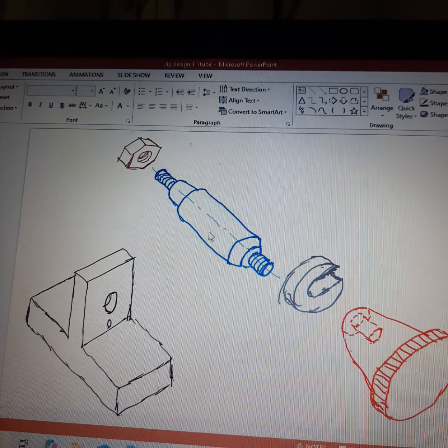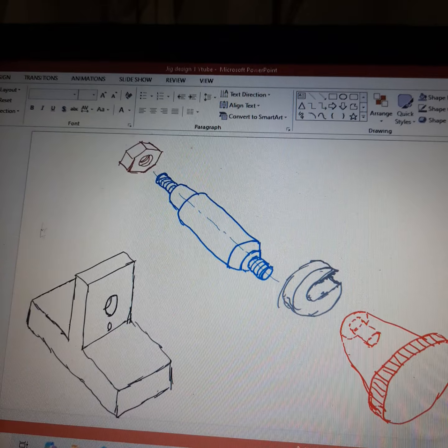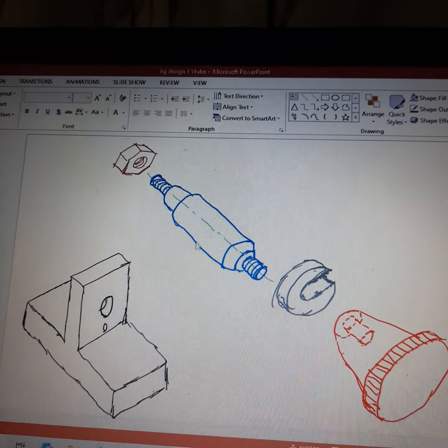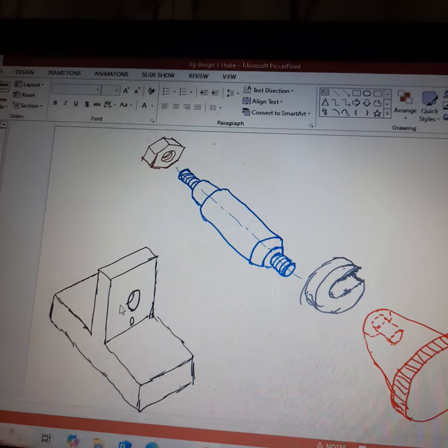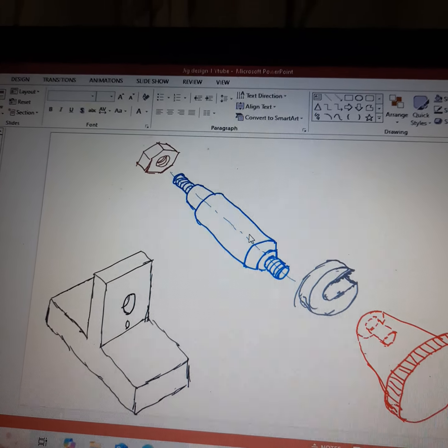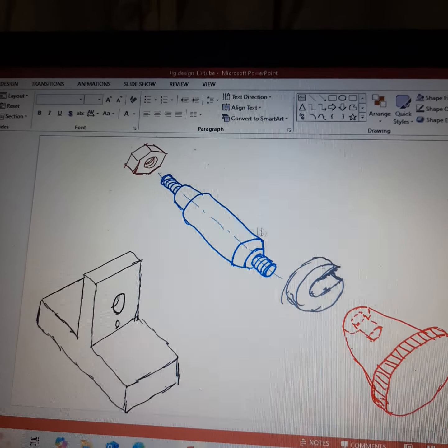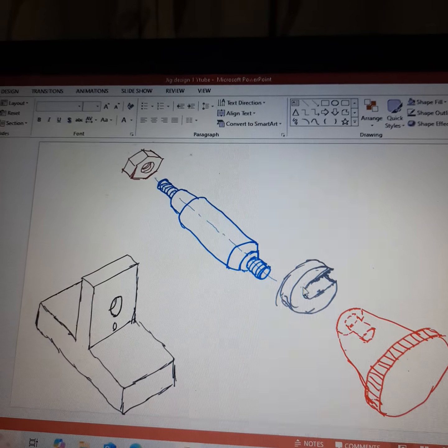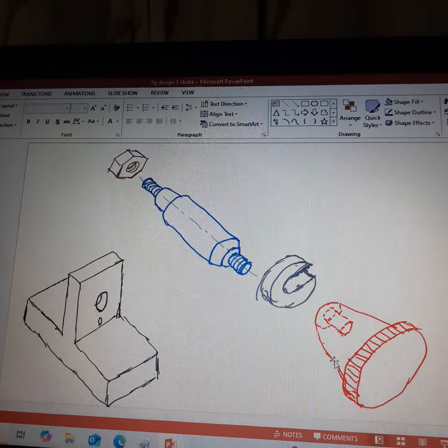On fitting this onto the vertical wall, from the other end we can use a washer and nut for holding the location post onto the vertical leg of the base. Once this is fitted, we can insert the component through this post, and for clamping we are using a C washer and a hand nut. So this is the C washer, this is the hand nut.